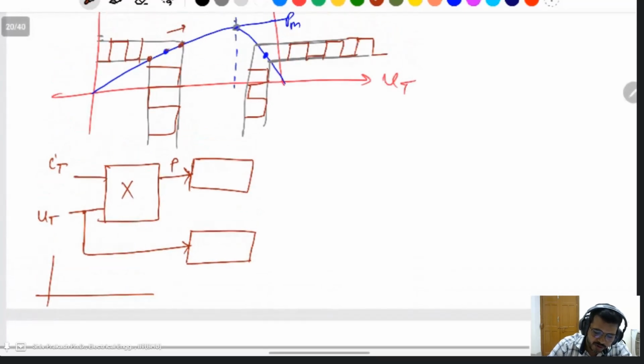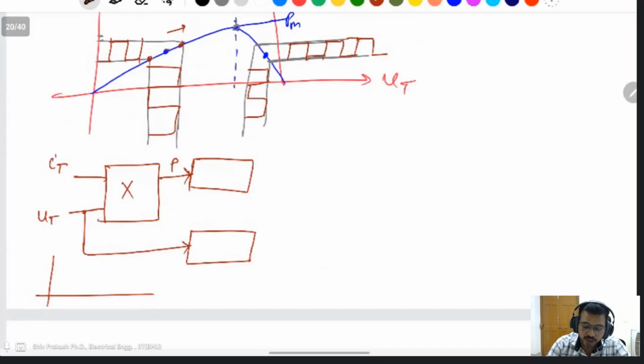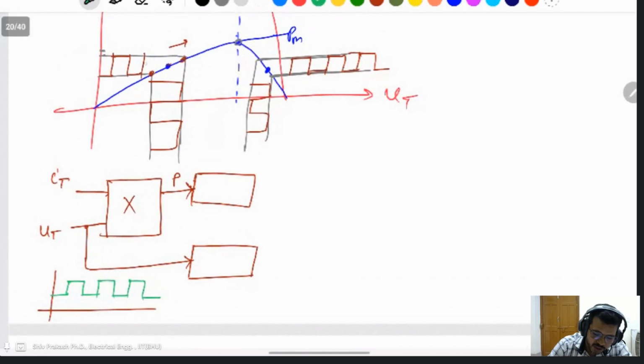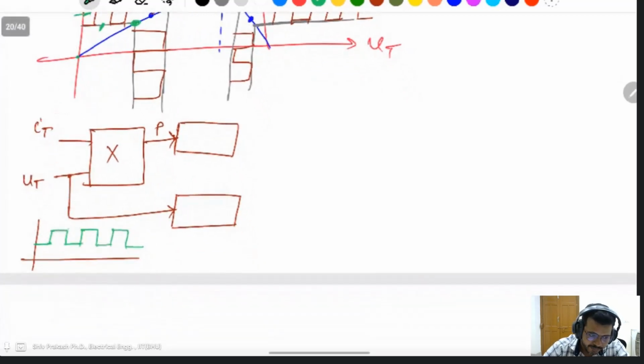If the switch is on and off, that's why you sense the voltages like that, in pulses. It will not be 0 because of where you sense here; if you sense here, some voltage is there. This is the higher voltage, this value, and this is the lower voltage, this value. Between these, you can get the same thing by passing through the DC block, subtracting the DC voltage.